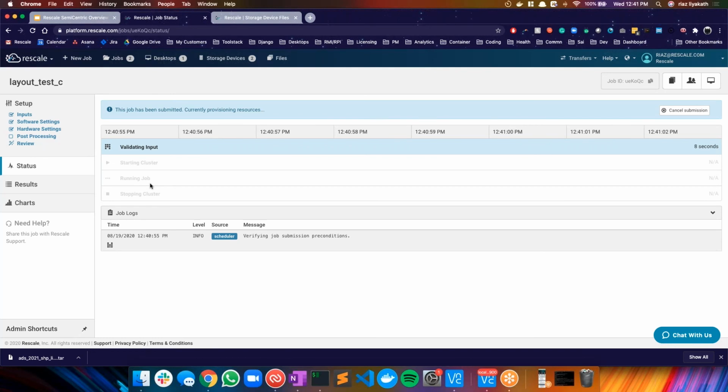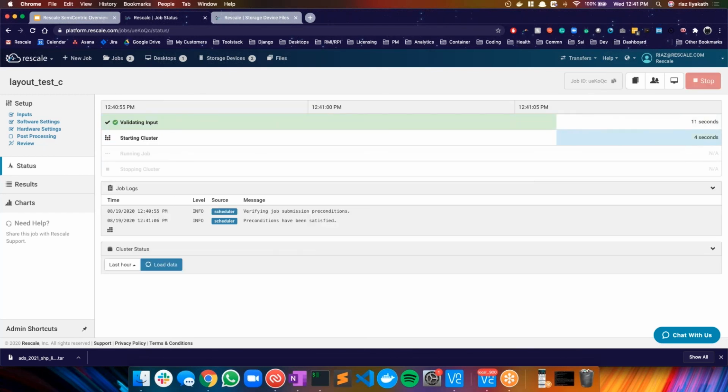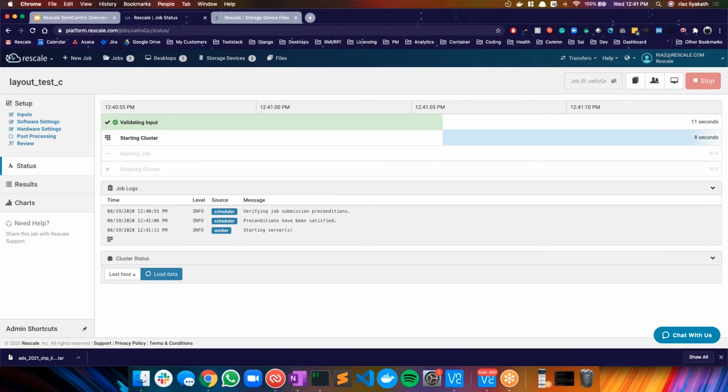So to recap, so far you've seen how we created a storage device. We launched a batch job. While this job is running, I want to go to step 3, where we are going to open Mentor Design Drive and RV in an interactive session, and then start pulling these database files so that we can do some verification, right? So let's actually go to step 3.